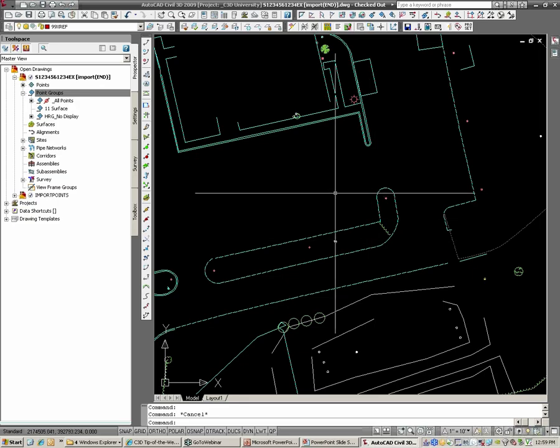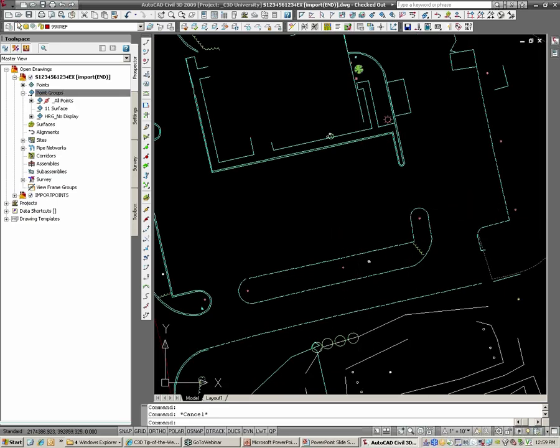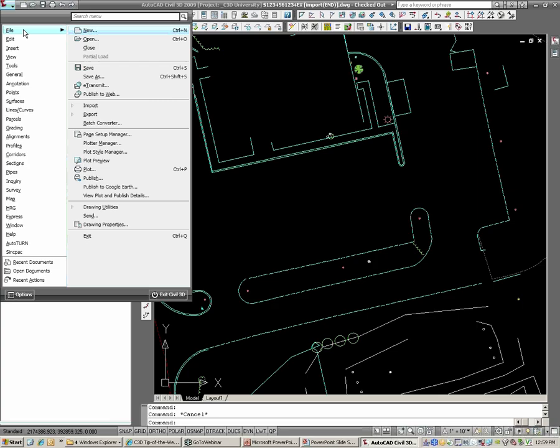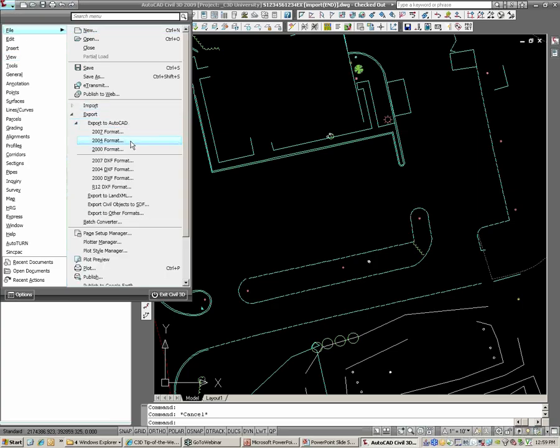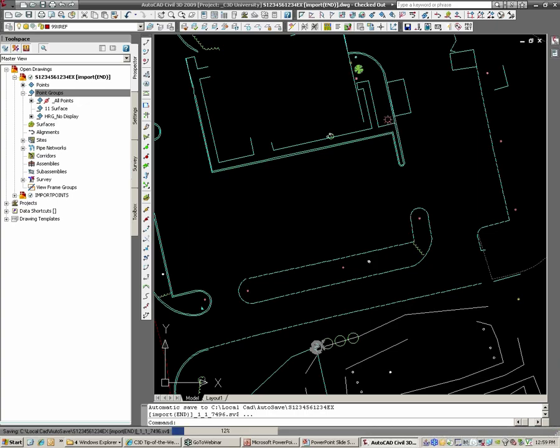This is also where it gets into that last post. If you need to export the project out at this point to give it to an outside source, you can simply go in here and hit export, and the only thing it's going to send them is the symbols you see on the screen, which we typically send out anyway. The points are still in the drawing. It's just not displaying the labels or the nodes for the other X points, for the grade shots and so on and so forth. So, little tip for you.